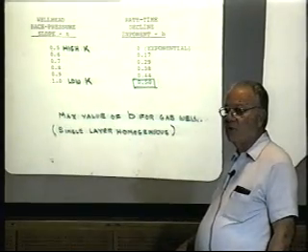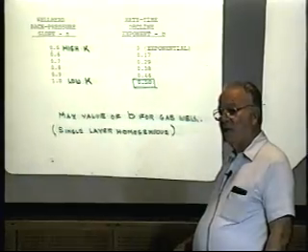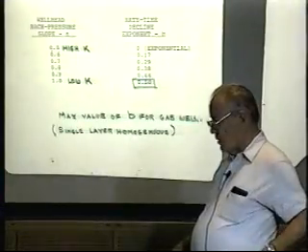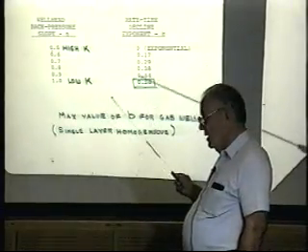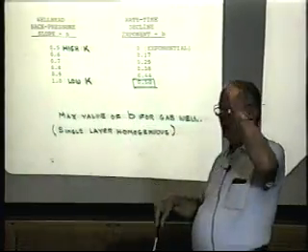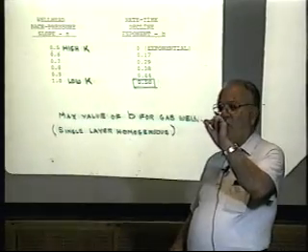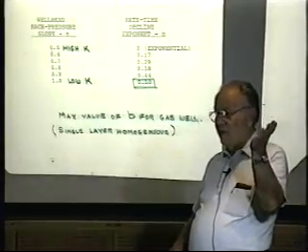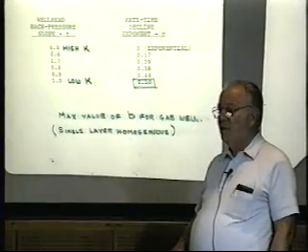There's an easy way also to calculate how long you can produce at a constant rate before you go on decline. You just take the back pressure equation with a line pressure. You go up the back pressure equation at the constant rate that you're going to produce. You get the shut-in pressure at which it's going to first go on decline. You go to your P over Z plot. You have to determine what the cumulative production would be over that period, and you divide that by the rate, and you get the time. And that's when you'd go on decline. You see that?